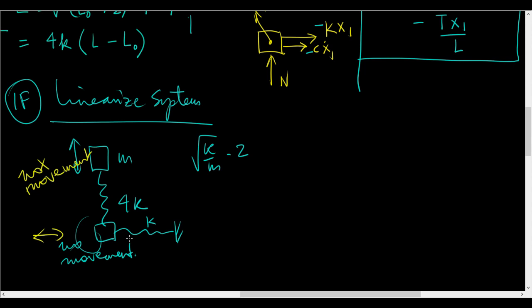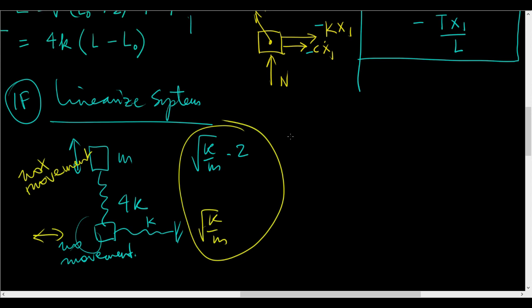And in this case the natural frequency is square root of k over m. So the ratio is an integer, it is 2:1. Such a simple rational ratio between two natural frequencies of two modes, the existence of such a simple ratio is called an internal resonance.